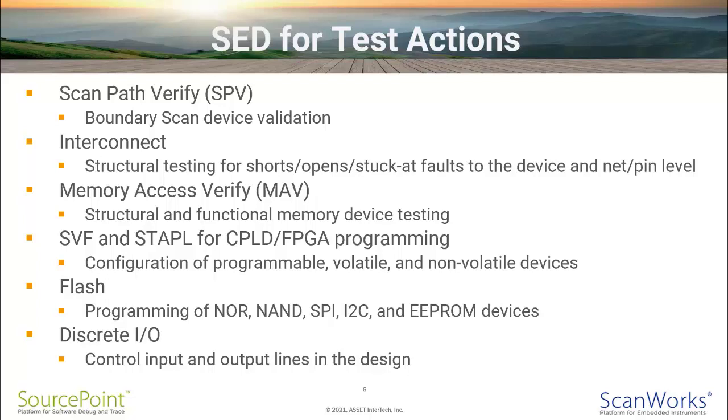There's a variety of programming options, whether you are configuring FPGAs or CPLDs using SVF or STAPL. For any flash devices on your PCB, whether those are NOR, NAND, SPI, or I2C, the flash action is available. And if there's any discrete I/O that needs to be controlled on the PCB as well, all of these actions are available for use within the SED for test technology.